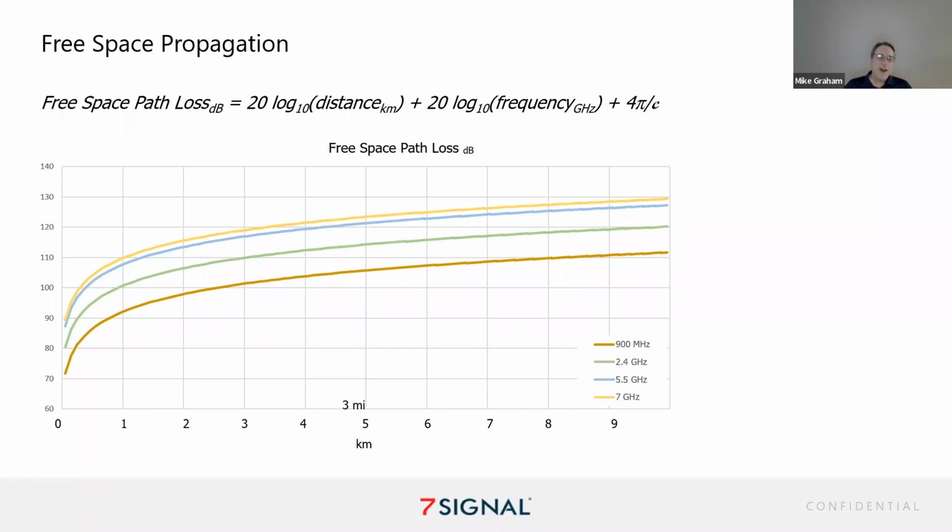And I was like 25 dB down from the prediction. What is going on here? I swapped cables and antennas, and I started doing dumb stuff like ungrounding because that was the change I had made. And eventually, after a few days, we discovered the polarization stickers on the client antennas were flipped 90 degrees. So that was upsetting. But from those point-to-point links, you can know what your signal strength should be. And if it's not, something's wrong.